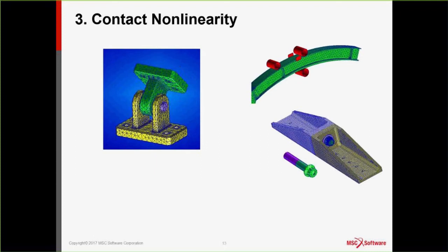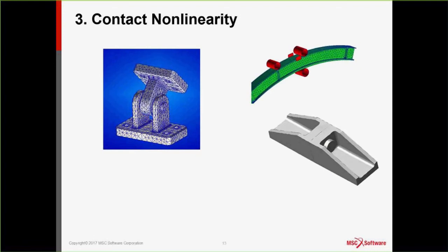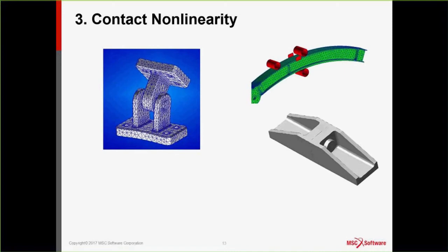How about a very typical tension joint, right? This is a primary joint, two bathtub fittings that's preloaded together with a bolt. In this case, we will actually apply a preload. I'm showing here, split the bolt, apply the preload, and clamp the structure together. And then we want to see when I apply the external load, does the joint gap? So again, I need to have the two bathtub fittings and the bolt as three separate contact bodies. And now I can simulate contact between the parts.